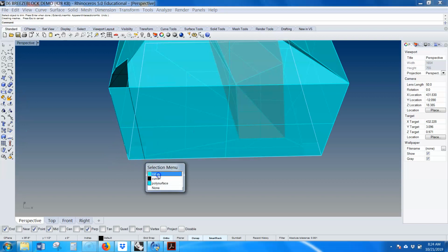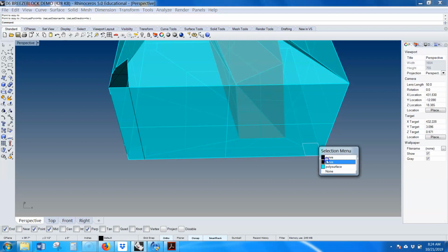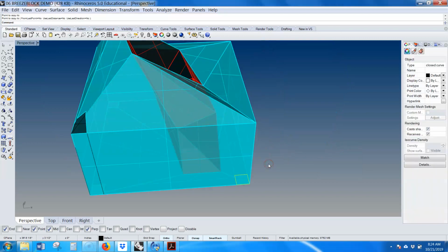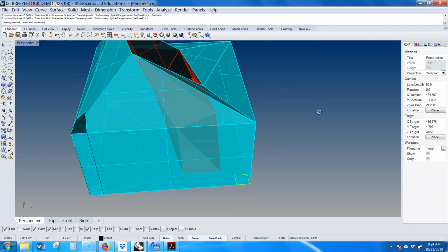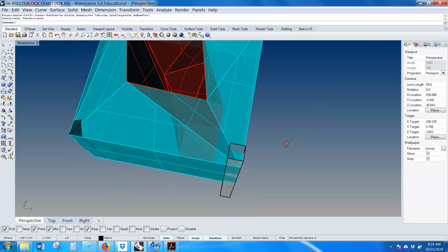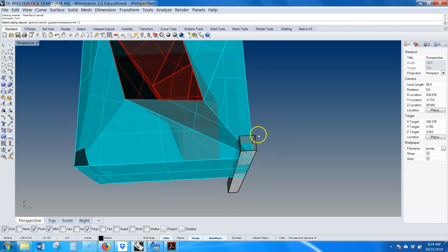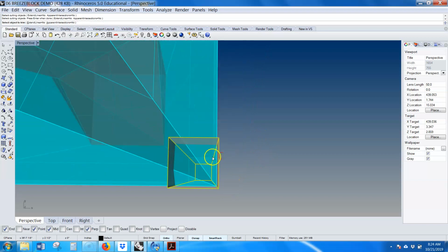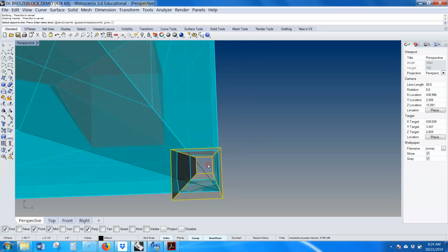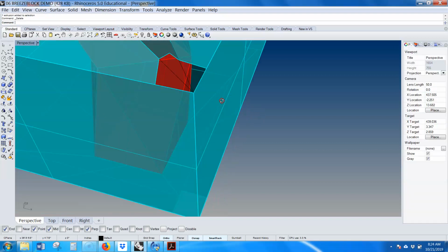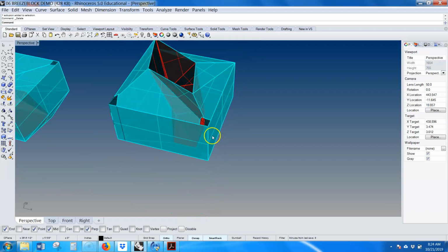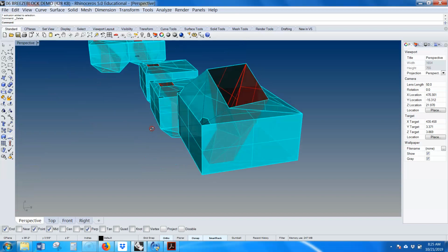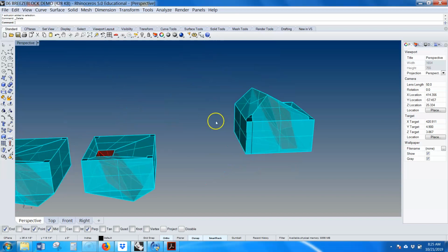Another way to do it. Can anyone think of another way to do this? Another way to do it is to do this. Extrude curve. Solid, we'll say no. Right? And now I can trim with that. Now watch what might happen as a result. Alright, that worked pretty good. Okay. If it were to take out a sliver from the side, just reconstruct the side. I'm a big fan of just manually modeling things in Rhino.